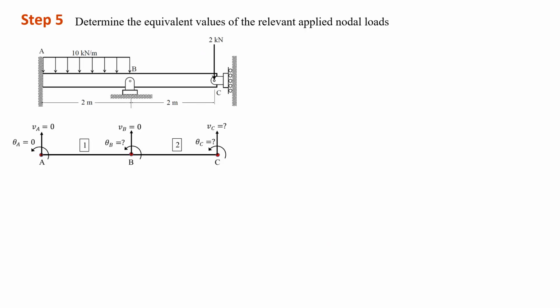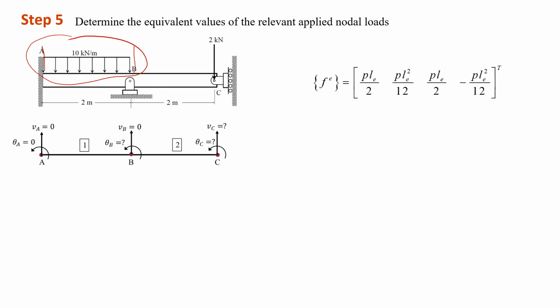Before we can proceed with the system of linear equations, in this problem, it has been applied with a distributed load between point A and point B. So the next step, we have to get the equivalent nodal forces at point A and point B. For that reason, we have to use these equations, and then we have to apply element by element. So element 1 is between A and B.